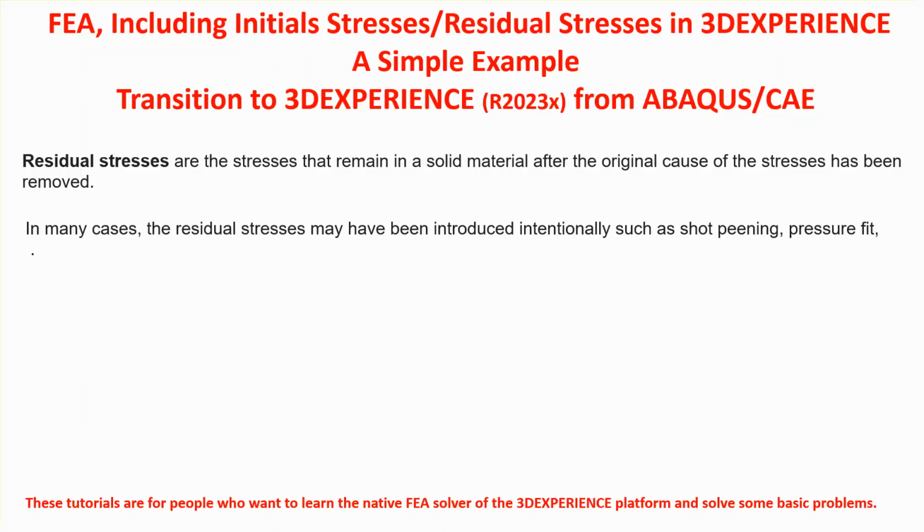cool down. So once that happens, the shaft is going to be under tensile outward stress, and the bearing is going to be under compressive stress, or the other way around, depending on how things are done. So these compressive and tensile stresses remain in the setup, but they are in equilibrium. That's why they're not causing too much of a problem.